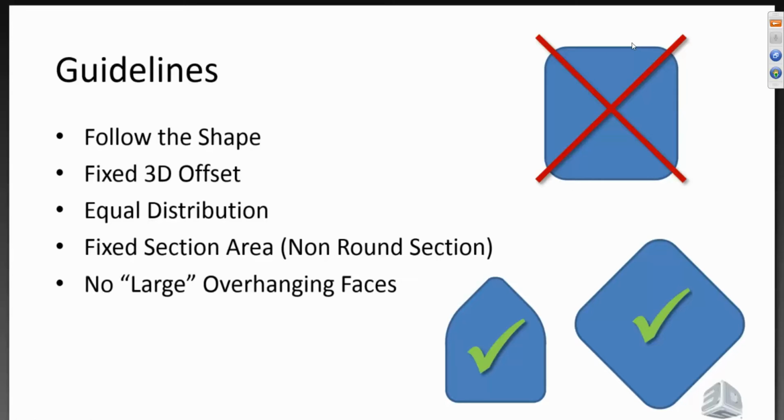Now you can compare that with turning it 45 degrees, where you see this angled wall, or putting a crown on it like this. Now as we layer across it, there's a little bit of an overhang there that it can grab a hold of for the next layer. And now we can successfully layer it up and keep the geometry of the water line as we've designed it. That's a real important thing to keep in mind, and it can vary from printer to printer depending upon what you have. So you have to know that about your printer.